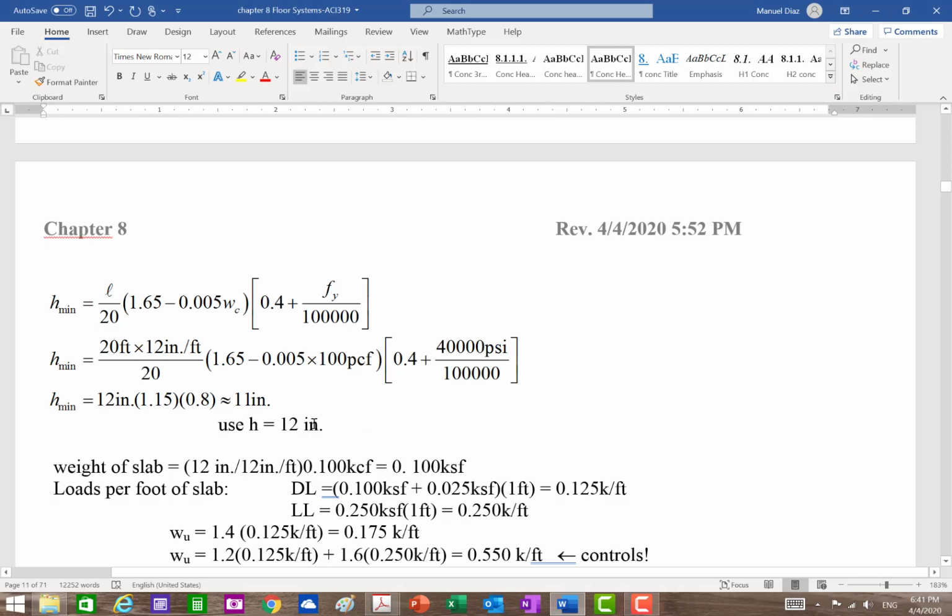Okay, and this is something that you're having issues with in your beam design, right? You're getting the numbers and you say, okay, well, I have to stay with that now. No, I mean, you can vary your values, 1 inch, 2 inches, right? To accommodate. The value is just the reference that you have to design your beams. The same here. This is a reference value. It doesn't mean I have to use that value. If I use less, all it means is I have to check deflections. If I use more, well, with more weight, maybe okay.